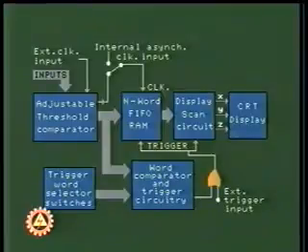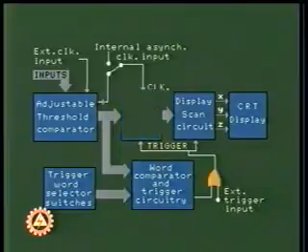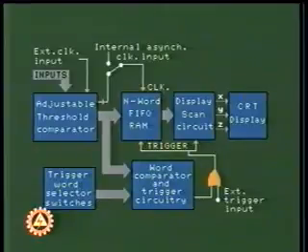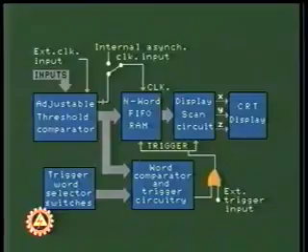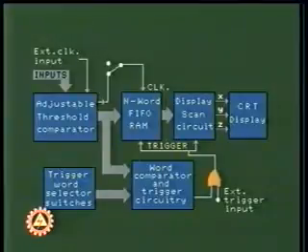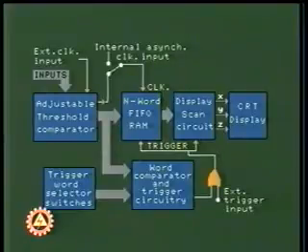The analyzer consists of a FIFO RAM for storing samples of the signals present in its data inputs, a clock source to synchronize samples of data input signals with the occurrence of a pulse, an internal crystal-controlled clock source for precise timing measurements, and a display scan circuit and a CRT display to display the group of samples on the screen.